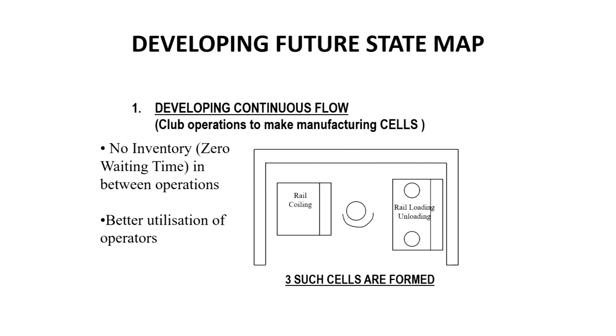So, now with this takt time and the pacemaker, we are developing the future state map. So, what can we do? We can use the cellular manufacturing concept: rather than the 2 stages being independent, we can convert them into a cell.